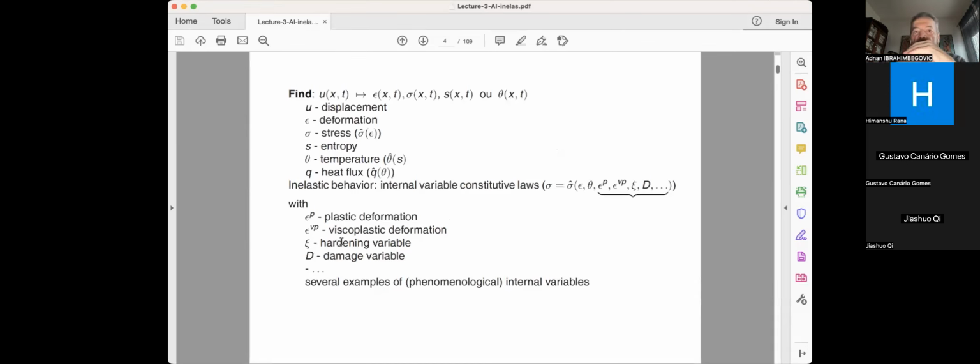Now, novelty is also the fields that we have to compute. First of all, we're going to be looking into the non-stationary problem, and everything will be not only a function of x, which is the space coordinate, but also of time. In other words, a non-stationary problem. We are going to be interested in starting heating at a certain point equal to 0, and then heating for a certain amount of time. Let's say on a weekend, you go skiing and you heat your chalet only for 3 days. So you have displacement, strain, and stress. These are the first 3 for the mechanics.